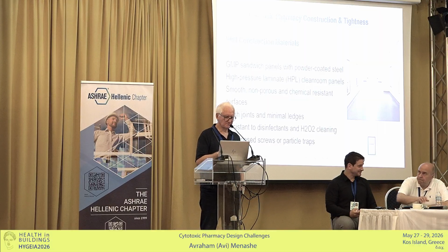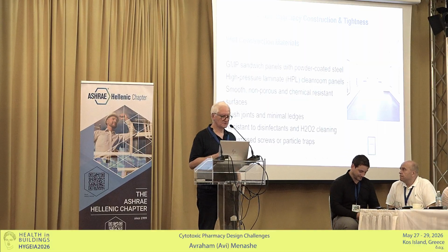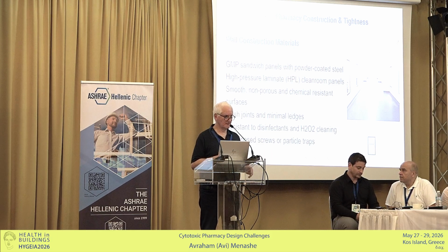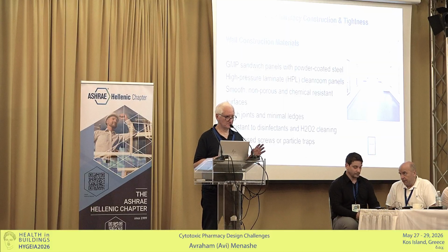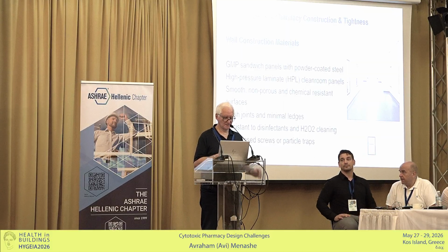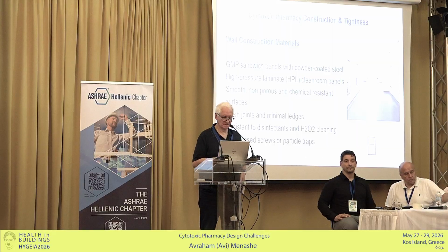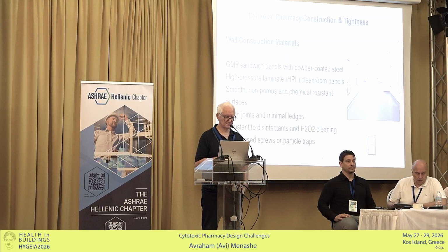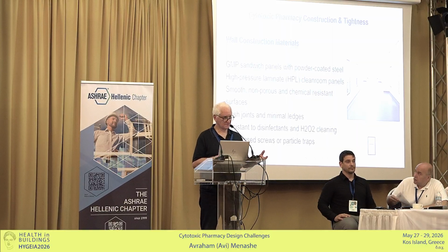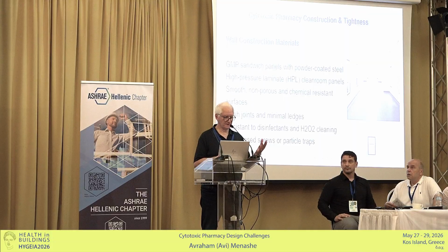Okay, so I spoke about the construction and the tightness. You should make a very sealed envelope, otherwise you don't have any chance to create the under pressure or the positive pressure. All the structure is normally made of HPL, a special sandwich of laminated clean room panels.